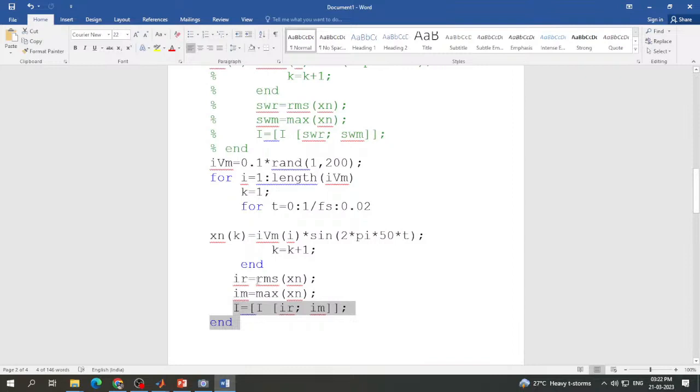No, these are inbuilt functions. RMS and maximum value are inbuilt in MATLAB, so not much effort you have to do. But if you are going for any signal processing technique, at that time you have to write a huge code for that particular signal processing, including integration, summation, and window function. And after that, whatever result you are getting, all the signal processing techniques are nearly giving a frequency domain component, so something like real plus j omega will be there.